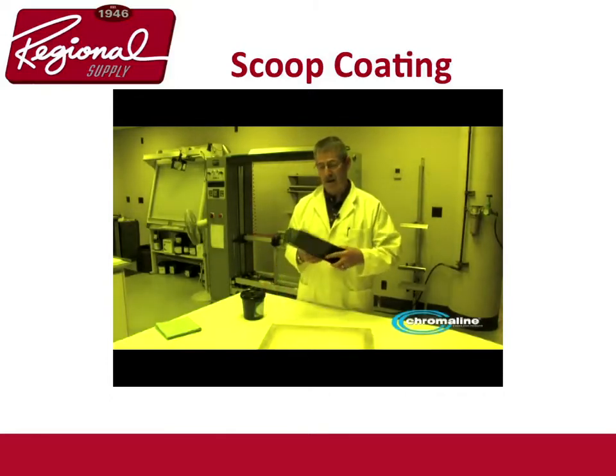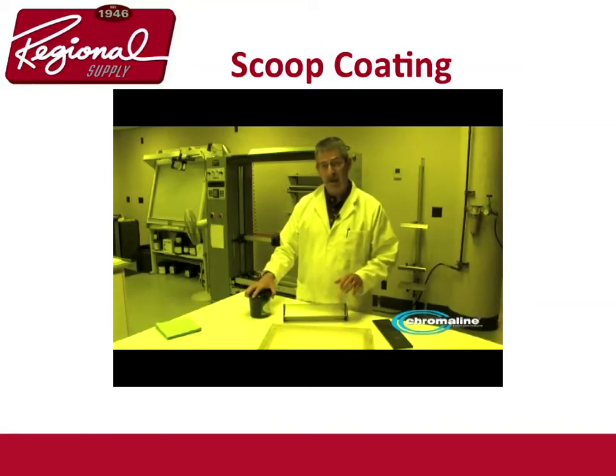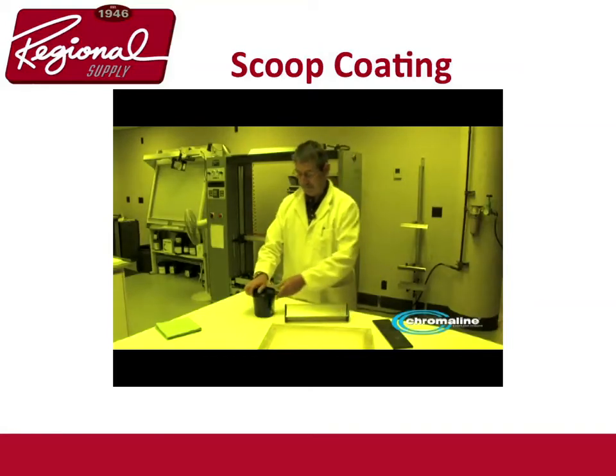Then you need a coating trough, or scoop coater as they're known in the US. This particular coating trough actually has 2 edges, a dull edge and a sharp edge. What we mostly use is the dull edge, because that puts a lot of emulsion onto the screen quickly. And being in production, you're always in a hurry. Now this emulsion's been properly sensitized and ready to go.